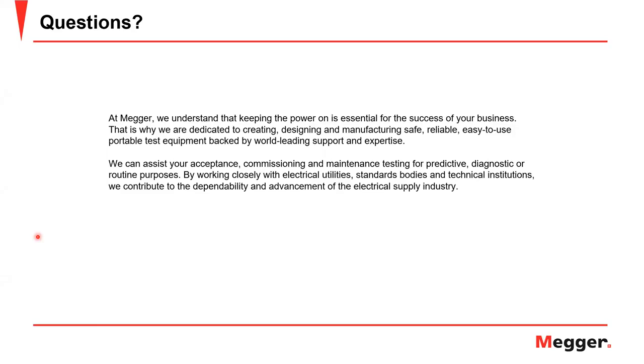And you can, I would say, selectively activate the single-phase and the three-phase reclosing of the recloser system that you are using. So the answer to that question is, you need to verify with a proper load and fault study, and with the types of loads that you have connected and the service level agreement you have with those customers, whether it is a good solution for you or not.